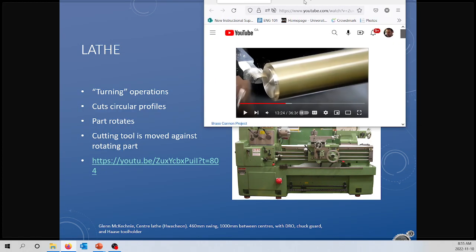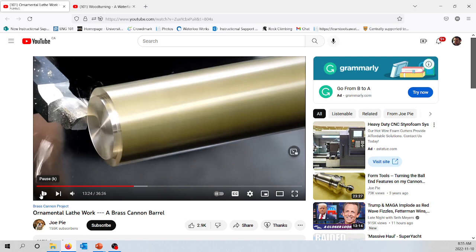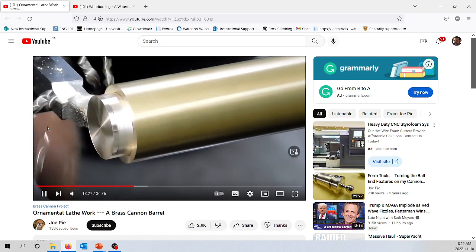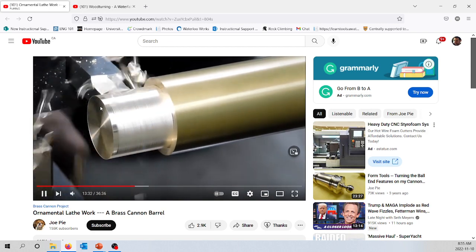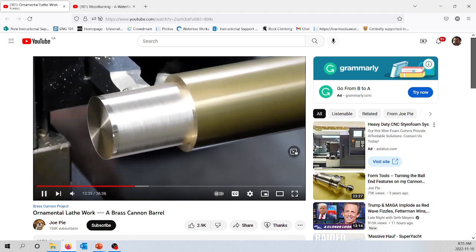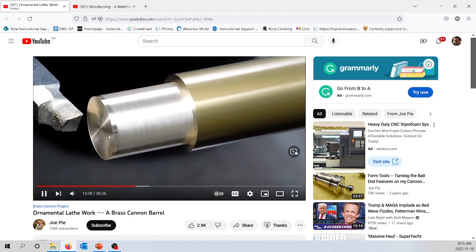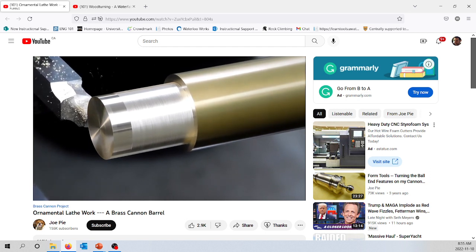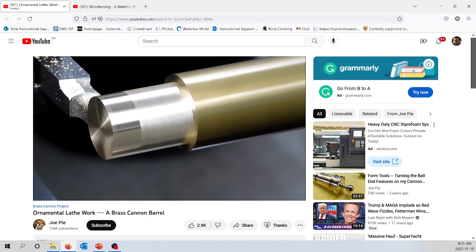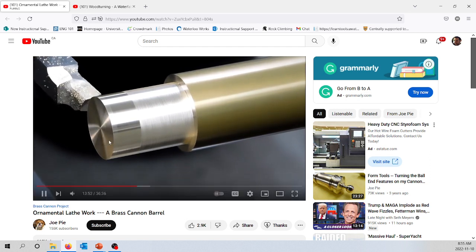Let's grab a very quick YouTube video of somebody cutting some brass with a lathe. You guys have played with the lathe, but you might not have been able to see that up close. So we have a cutter. This is from the back. We've got a cutter moving against stock, and as it moves along and presses into the material, it's doing a roughing pass and a finishing pass. Roughing pass, they took off like 1/16 of an inch. Now they're taking off a couple thou, and they're just moving that cutter in and out using the dials on the lathe.